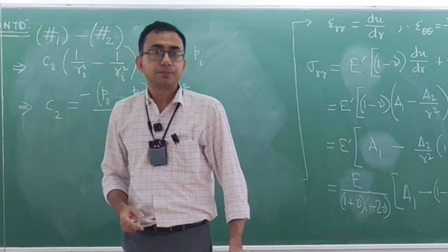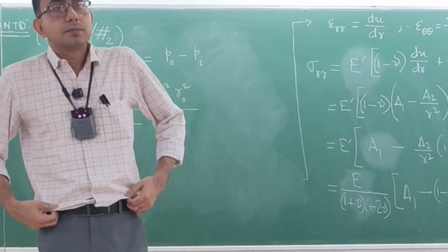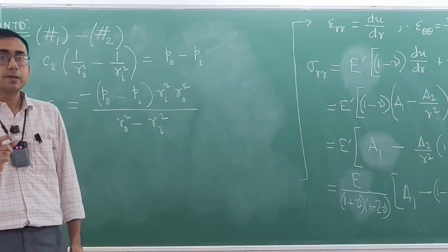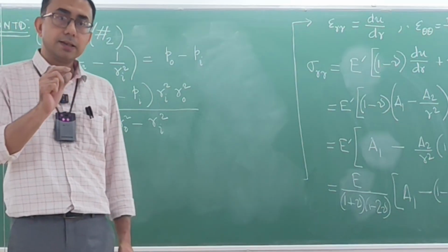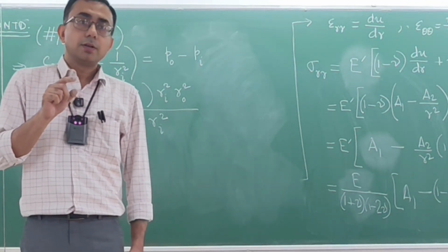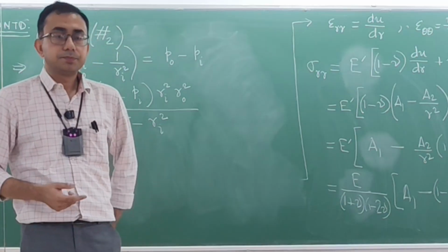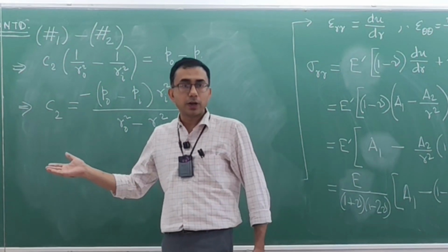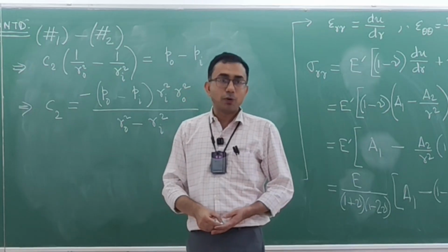Yes, Charit. We are discussing thick walled pressure vessels. Yes. So where is thick wall? So the thick walled means that there is significant difference between the Ri and the Ro. So Ro minus Ri is still the thickness. It is T. If I shrink Ri to R, then it will become the case of the thin walled pressure vessel. Okay. So you see, for the thick walled pressure vessel, so much we had to do, but for the thin walled pressure vessel, just like a very small derivation, right?